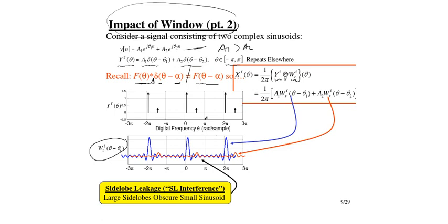So you can see that this blue curve is showing you the impulses shifted at these higher peaks, right? So this is shown here also. So what we did actually, A1 is as it is, and your W1 is shifted at theta1, right? Because there was a delta here, so W1 is shifted at delta. So what was W? W was this sinc function, which is shifted at theta1. So every higher peak which is shown in blue color is due to this peak, right?